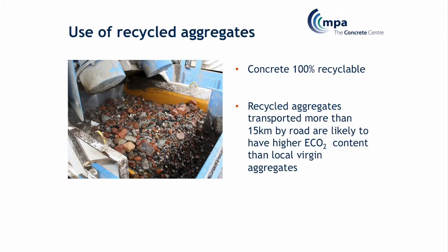Now, the difficulty is that actually we're already really good at using recycled concrete and recycled aggregate within the UK, 3 times better than the rest of Europe. It's very hard to get hold of it. Concrete is 100% recyclable, but it tends to get used in hardcore or various other different uses, very usefully around the building. Often it gets demolished and then put in the landscaping, for example.